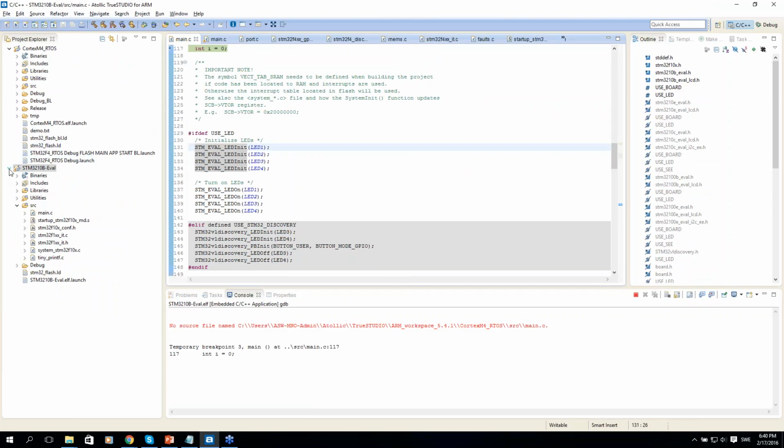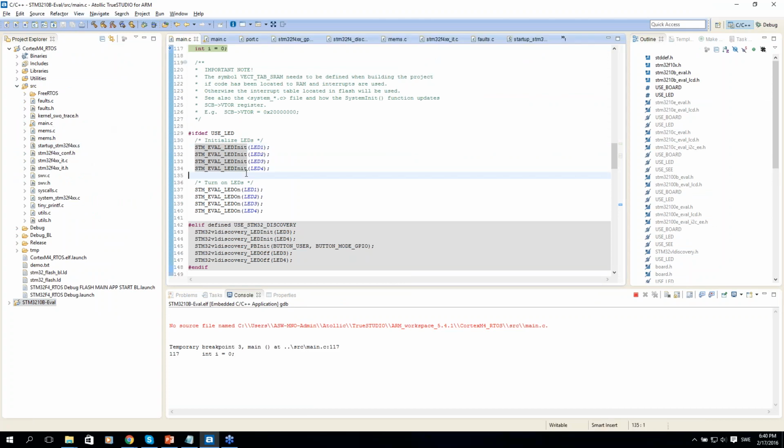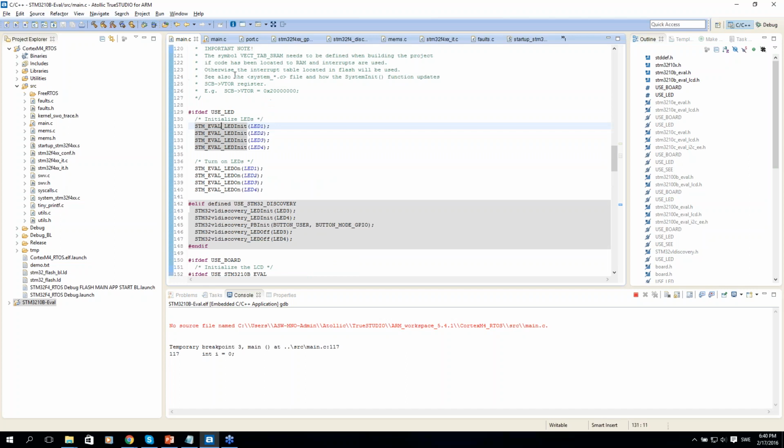You can do it in different ways. By default, printf is set up in the CMSIS core libraries, actually. This is an enforcement by the ARM CMSIS team to print printf statements to port 0. Let me see if I can find that. So let's take a look at how this happens.